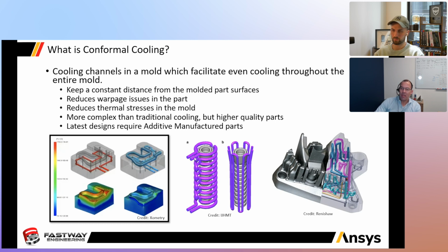There's so many different ways that we can create this cooling circuit geometry and try to maintain it. So what are the other ways we might optimize? I'm here on the left-hand side, I'm optimizing for mold temperature. The other things I might be optimizing for are minimizing the flow rate, so I don't have to have as massive a pump, minimizing the pressure drop, right?